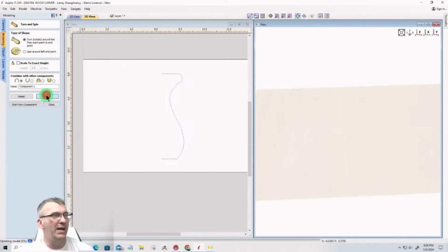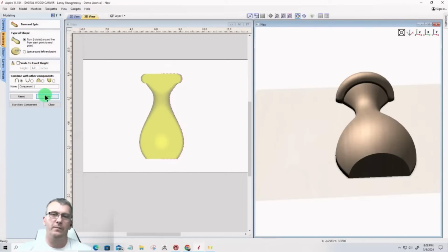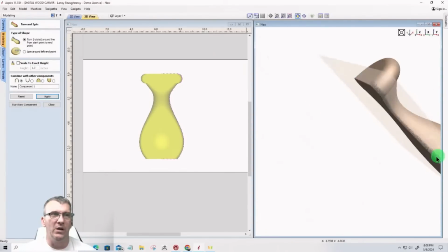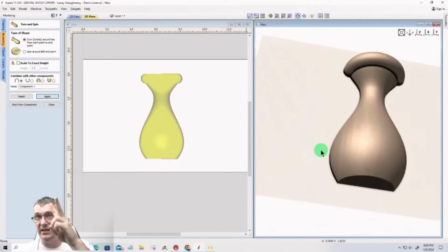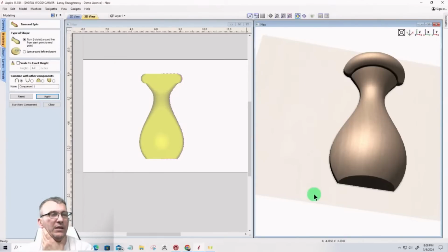And when I click apply, it's going to take that profile and just sweep it over. Okay. 180 degrees. Right. Now, if I was working with a two-sided project, I could copy that to the other side to create a full 360-degree vessel for something like the fourth axis or what have you, and that kind of effect, type of thing.